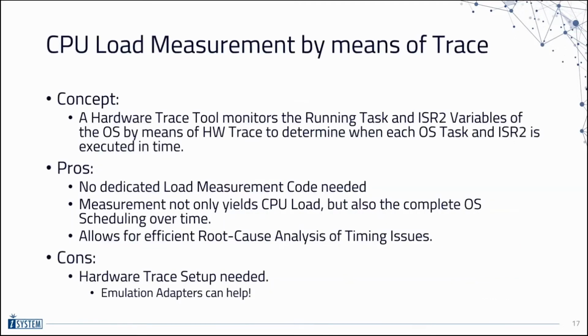While the two previous methods used extra code to measure CPU time to calculate CPU load, which is overhead, the remaining methods require no code instrumentation and instead use a combination of the microcontroller and the debug tool to measure executing and idle time.